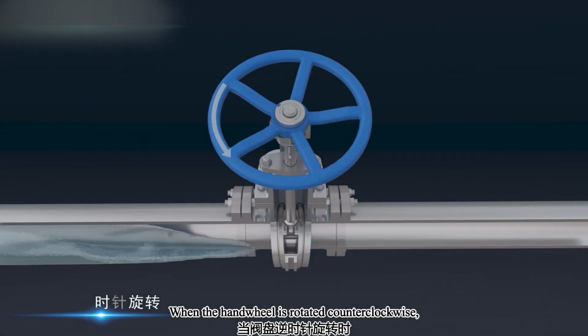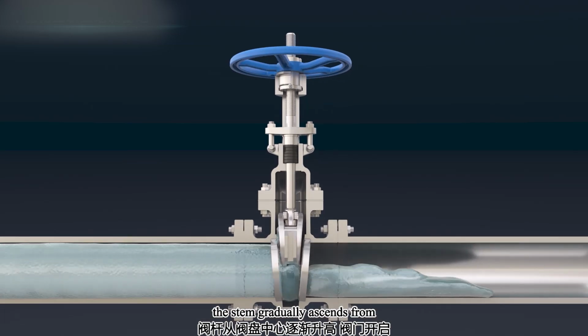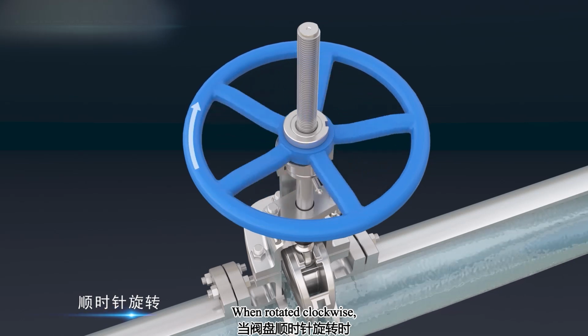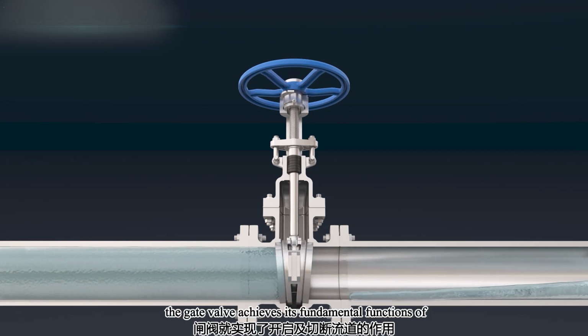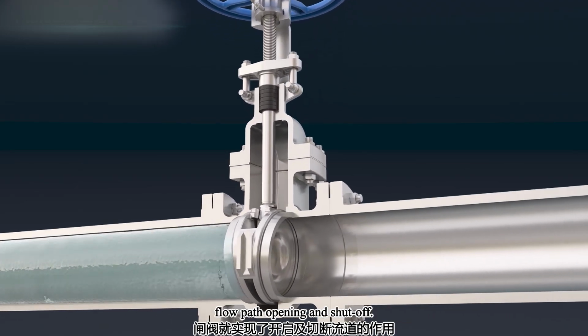When the hand wheel is rotated counterclockwise, the stem gradually ascends from the valve center, opening the valve. When rotated clockwise, the stem progressively descends, closing the valve. Through this mechanism, the gate valve achieves its fundamental functions of flow path opening and shutoff.